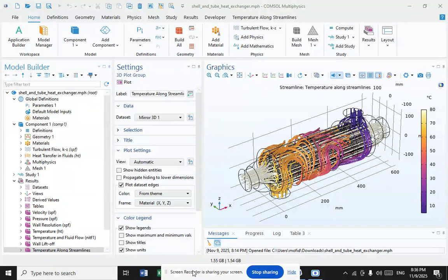The other main type of baffle is the disc and donut baffle, which consists of two concentric baffles. An outer wide baffle looks like a donut, whilst the inner baffle is shaped like a disc. This type of baffle forces the fluid to pass around each side of the disc, then through the donut baffle, generating a different type of fluid flow.